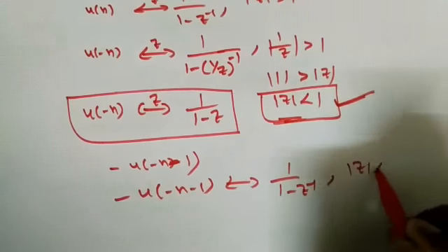The next property is the convolution property, a very important property. When we analyze LTI systems, we have to do the convolution. When we want to find the output response, we can take the z transform, then do a multiplication, and then we can easily get the output response. So what the convolution property tells us is that convolution in the time domain is always multiplication in the z domain, that is x1 of z into x2 of z.